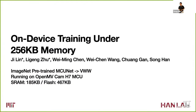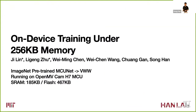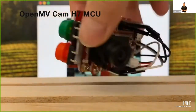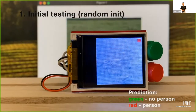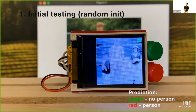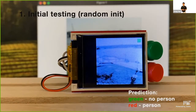With that technique, we have a demo here of on-device training under 256 kilobytes of memory. It's running on the OpenMV CAM microcontroller. Here we attached 2 buttons to input the class. We have a green button indicating there's no person, and a red button indicating there is a person. Initially, the model didn't have any training for these 2 classes, so the classification result is wrong. You can see the red or green showing on the top right corner of the screen. Before training, it cannot distinguish person versus no person.